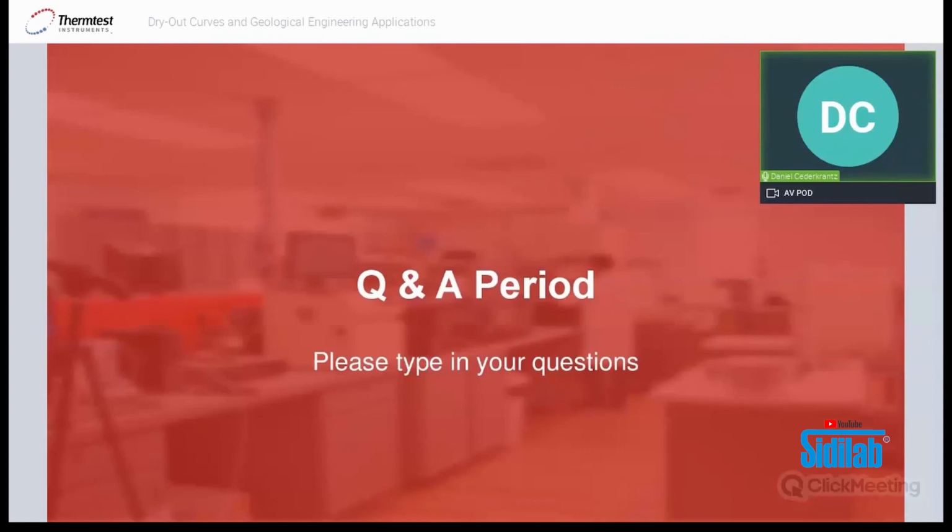It's used by the phase change. So you will get a strange behavior just in this melting range of temperature. So testing a few degrees away from zero is usually advised. You can test at zero, but you might get a little bit strange results there, and that basically shows that, yes, sample is melting here.